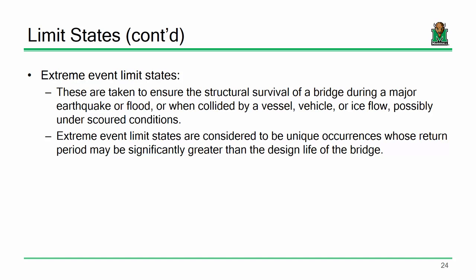We place structural fuses inside buildings whose purpose is to fail and absorb that energy so that the building doesn't fall down. Or, going back to my car crash example, okay? Let's say we're designing vehicles. If you wanted to design a vehicle that remained elastic after a car crash, that sort of acted like a bouncy ball, you took that car, slammed it into the wall, and it didn't have any deformation.